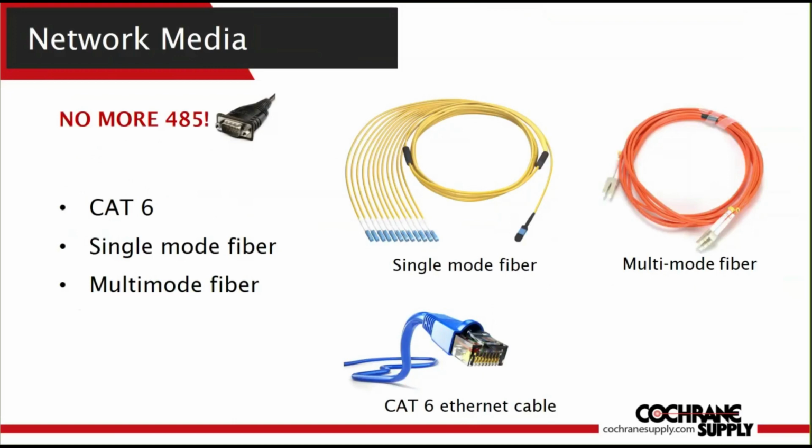So now we're talking Cat6, single mode fiber, multi-mode fiber. Those are your 3 options that you have when you're talking about networking an OT solution, right? So if you look to the top left, single mode fiber, that's typically what you're looking at, right? And there's a different school of thought for which actual media you want to use. But when you look at some of these solutions, some of them use a combination of single mode fiber and Cat6. It depends on the application.